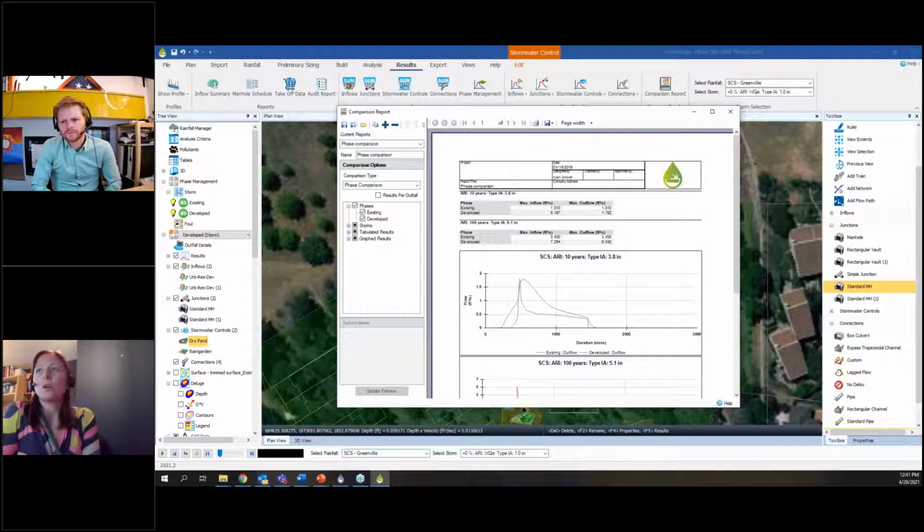But there was also a question about Civil3D more specifically, and we haven't gone into that today, but there's an integration with Civil3D that allows you to create an InfoDrainage network from a Civil3D pipe network and use their parts mapping to map from a Civil3D pipe network into InfoDrainage, and then actually go back the other way and update a Civil3D network from an InfoDrainage file as well.